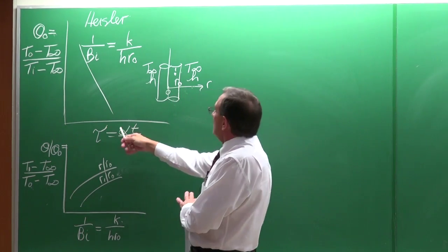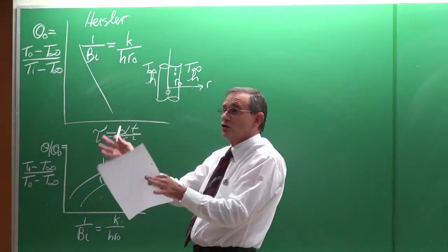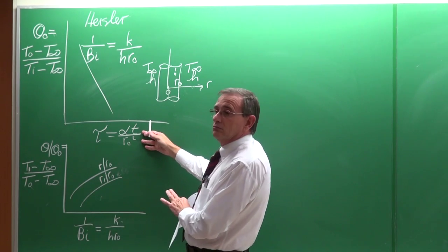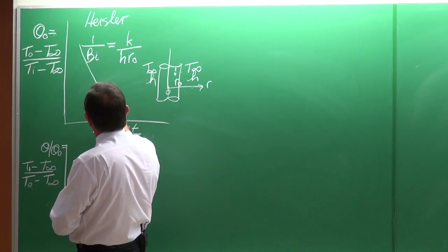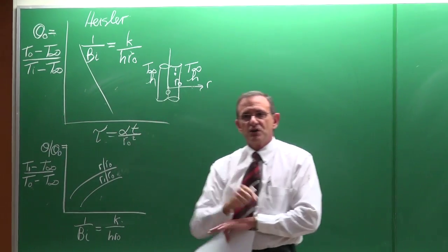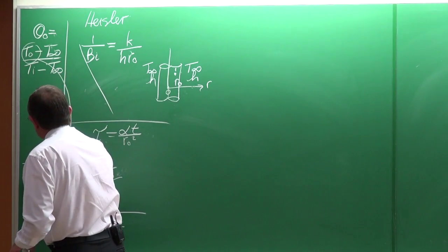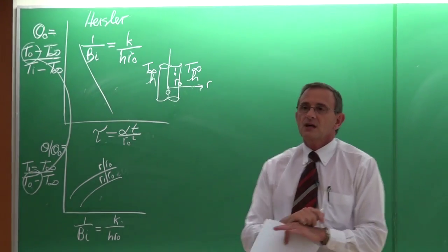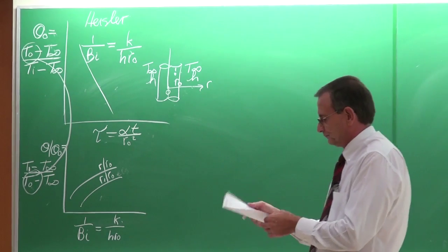So if you look at this graph, you can calculate the Biot number if the environment conditions are given. The radius, of course, is given. You want it maybe at 3 hours or something like that. So after 3 hours, you can go and get the non-dimensionalized time. You can get the Biot number and you can get the center temperature. Once you've got the center temperature, then you can put it in there and you can get the temperature at any point you're interested in. So it is a very easy solution on a graph.